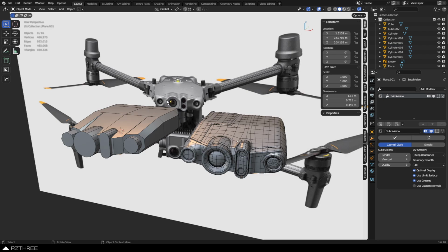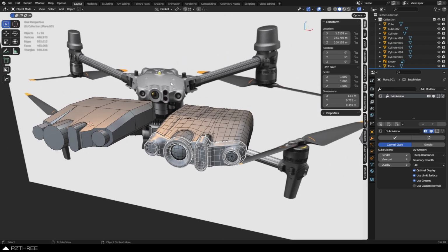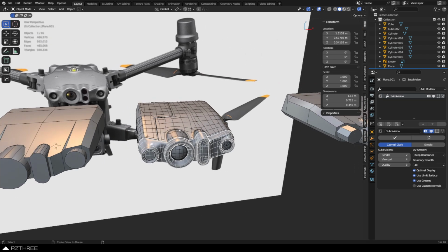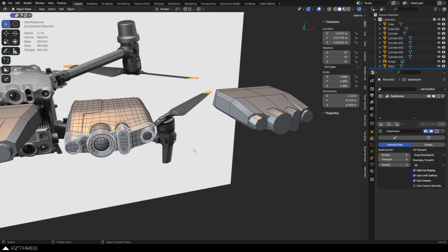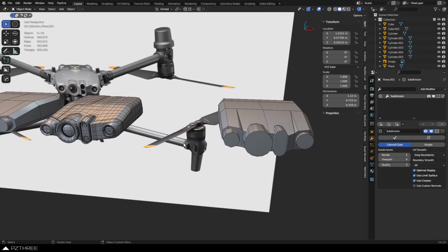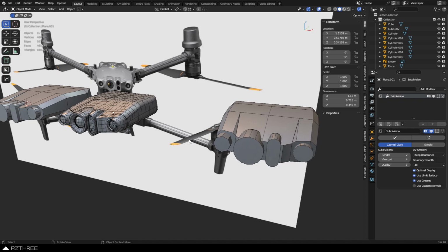However, when this thing is actually designed, it's probably done in CAD software. And this kind of split here is probably done later on. So the big shape overall is designed first, and then they break it into the little parts and pieces and sections perhaps later on, just to make sure they're going to work with 2-part molds and things like that. So 2-part molds can be just one way that manufacturers go about things. There's 3-part molds, there's more parts. And that's something to just keep in mind. Those are usually aluminum blocks that are machined out, and that happens quite a bit.